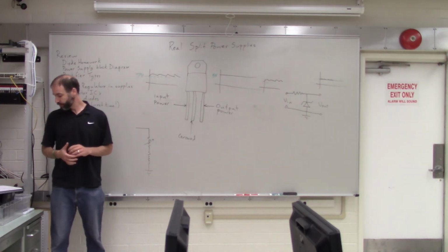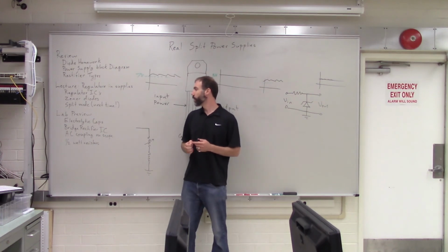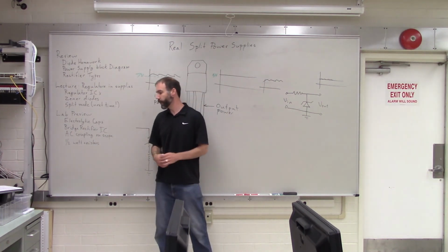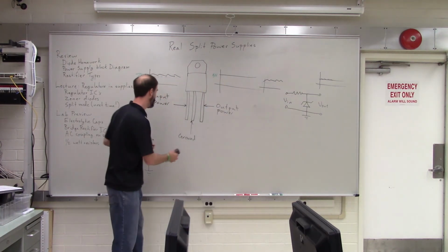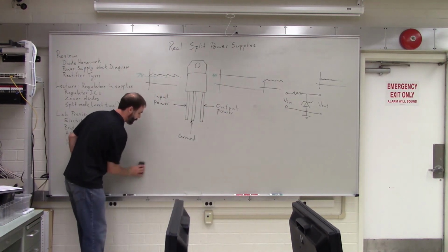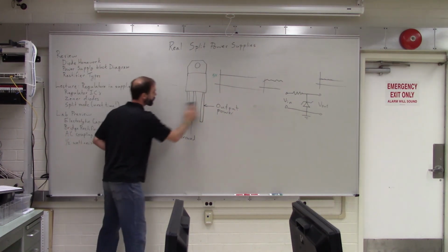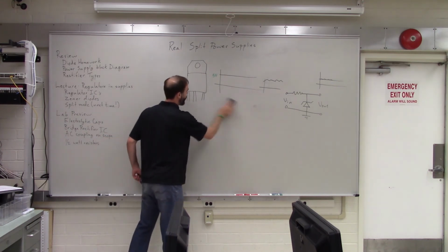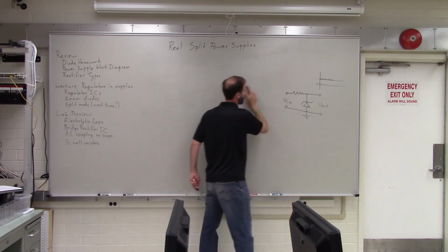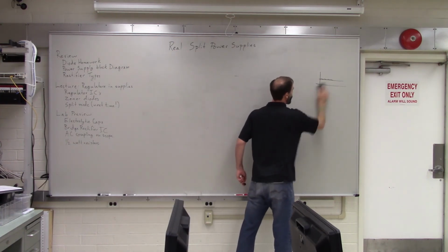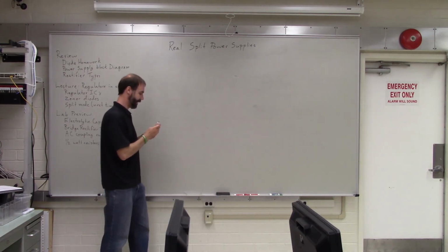Okay. So for the lab tonight, I wanted to briefly review electrolytic capacitors. So we're going to be using electrolytic capacitors as the filtering portion of our power supplies here. And electrolytic capacitors can explode if they get plugged in backwards. So let's take a minute and review.